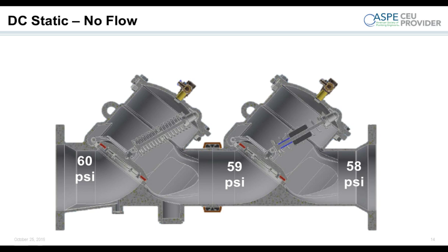Oh, we have a question about how the double checks are being tested. Sure, when people are testing a double check, it depends on exactly which standard you test to. Up here in Massachusetts, where I am, we have the NEWWA. You might be using ASSE tests or the USC tests or the TRIO test. But essentially they're looking to make sure that each of those checks is holding that 1 psi differential.